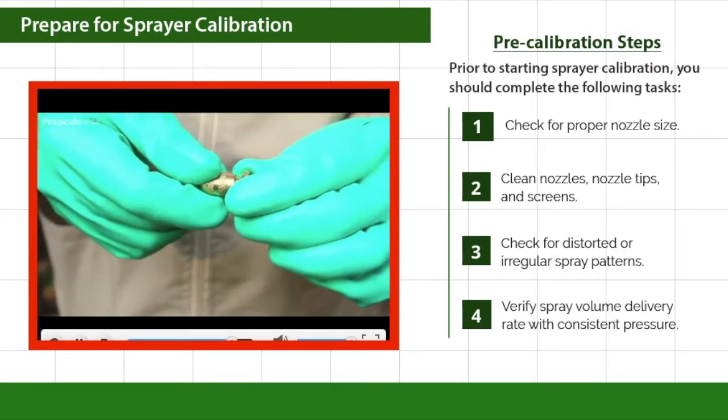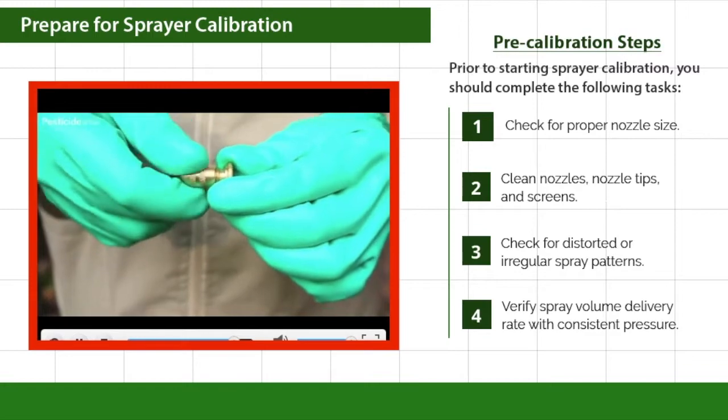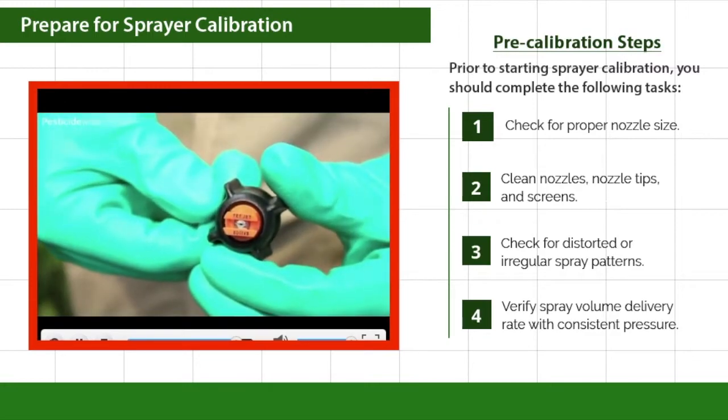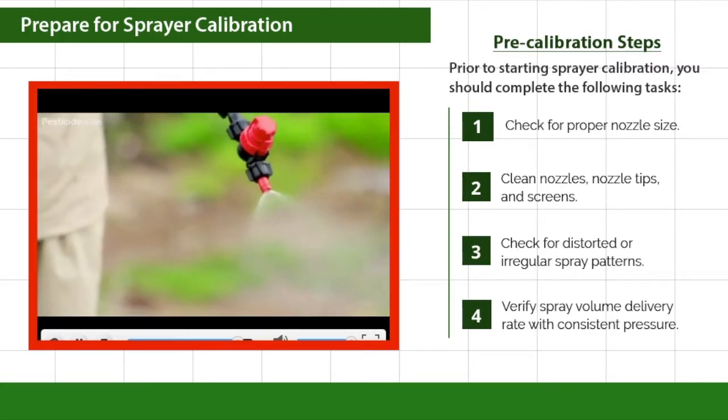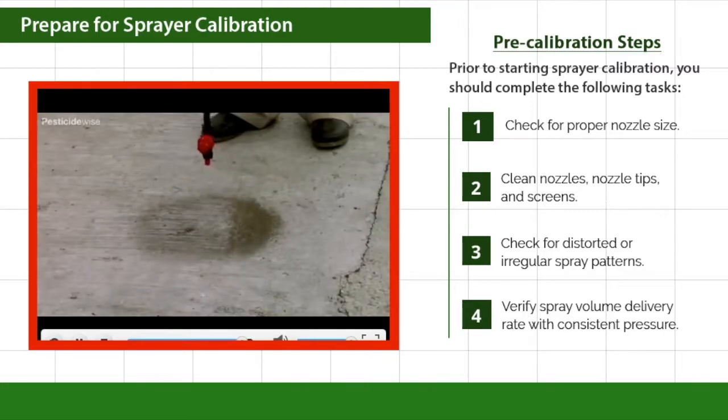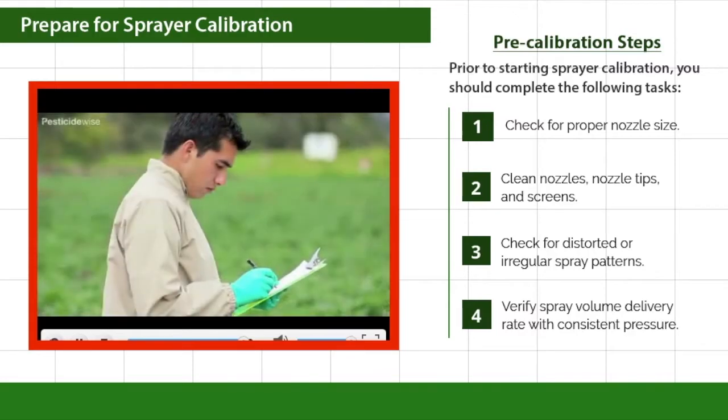Sometimes the knapsack sprayer will be sold with just one nozzle of an adjustable type. Others may come with different types of nozzles. Using clean water, check that the nozzle that you are going to use produces the correct spray pattern. Remember to mark up your checklist.